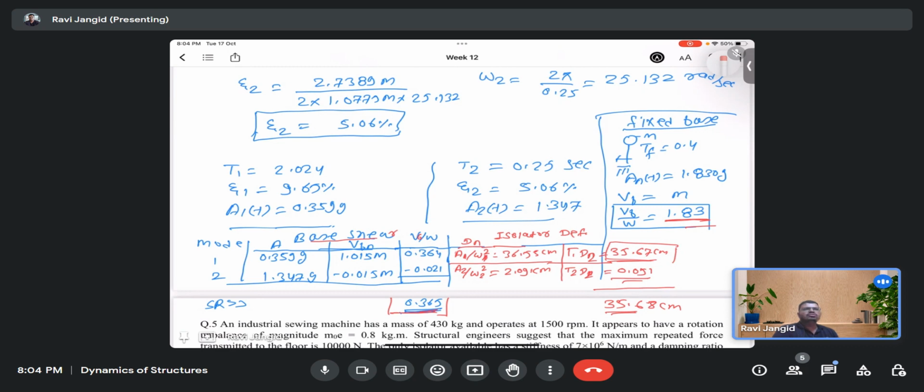Let us suppose you want to vibrate your structure in the first mode. So what you can do is apply the frequency at that particular modal frequency for the particular mode, and then you measure the displacement at each floor. After getting that, you can make a plot of how the structure's shape looks. In the graph you can show, for example, your three-story structure, and then you can find out how the data comes out. That is the thing, I think.